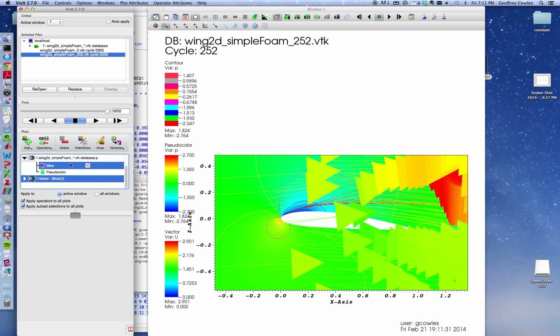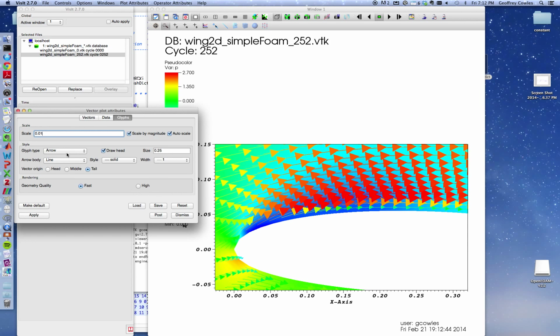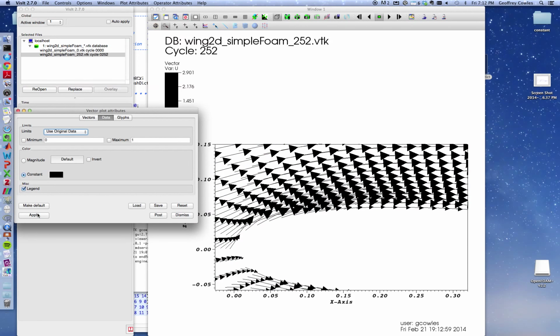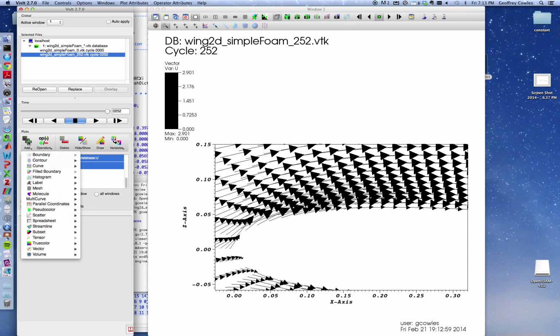Contours there. Okay. So this is the velocity distribution over the airfoil. If I zoom in right in the boundary layer, it's hard to see. Let me go back and change the vector magnitude again. 1. Okay, so you can see the velocity. Actually, I apologize. Let me put the velocity distribution behind there. I'm going to make my vectors all black. And I'm going to put pseudo-color velocity magnitude. Okay, that's better. So we're coloring with velocity magnitude.